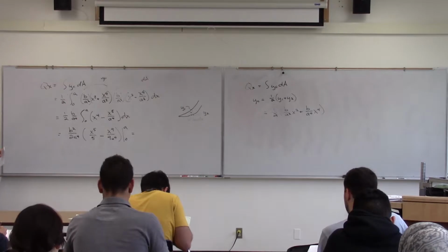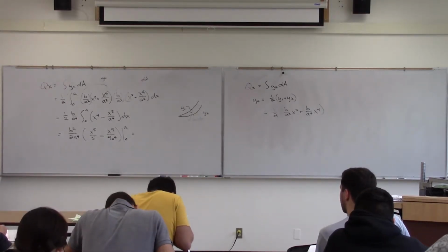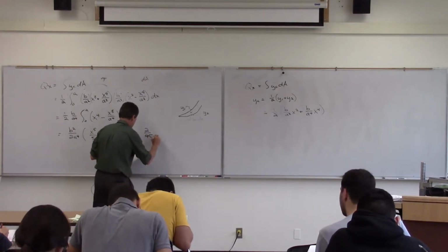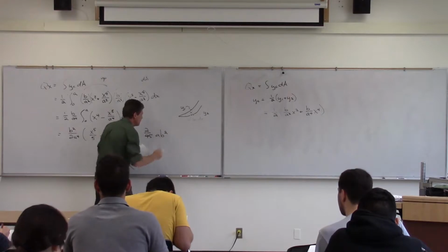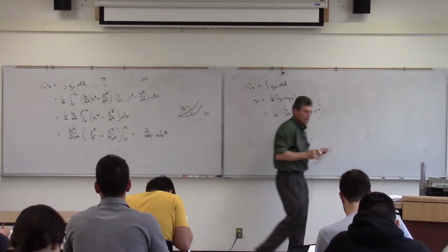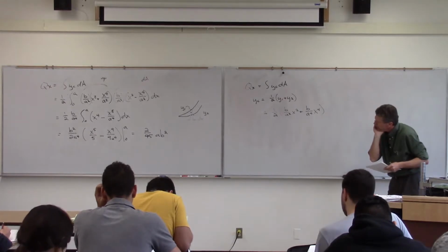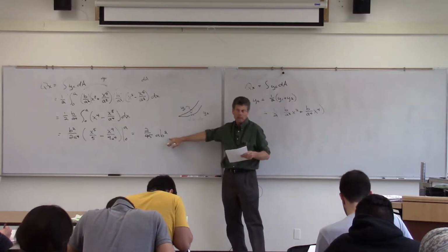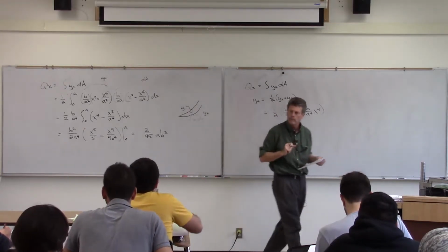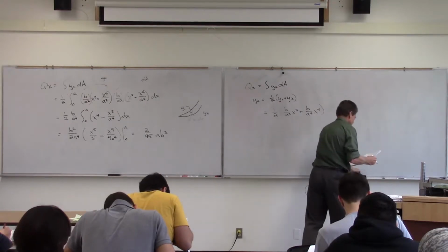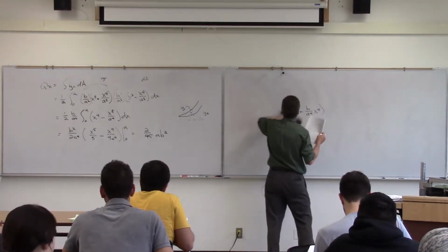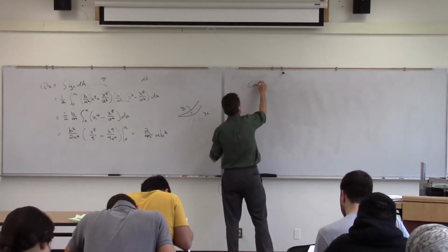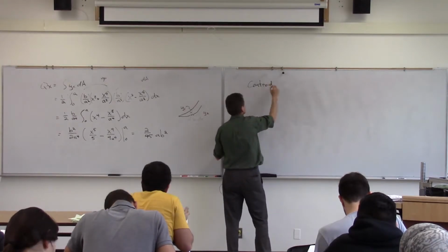And then just simply doing the integrations like we've done before. Just take those exponents, increase them. And what we find then is that we end up with, again, a simple term, but again, first moment of area, so we've got area times the length, or basically length to the third. Okay, where we're going with that is we want our centroids.